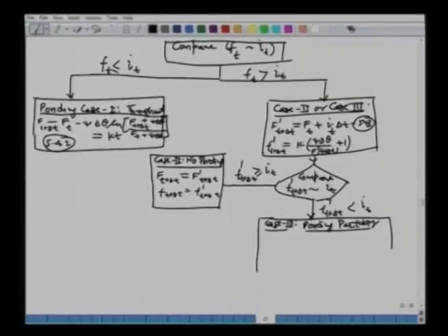So, what we are going to do is I will write the set of equations. What we need to do in case 3 is determine the exact time when the ponding starts within that time interval delta t. So, let us say your delta t is 1 hour, and you are into the 5th hour. During the 4th hour to 5th hour, exactly when the ponding starts, that is what we want to find out, and we will call that a variable called delta t prime. And once we find the delta t prime, then we can calculate the infiltration. Everything before that is whatever rainfall falls, after that we use the Green-Ampt equations.